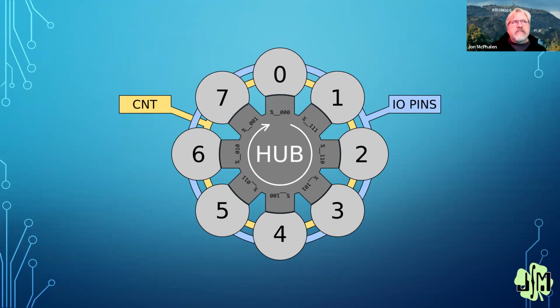And he has 16 channels of analog that he is using an external ADC because he already had that circuitry set up. And before, we needed 2 cogs to be able to read the ADCs and do a running average. So we actually will take the last 4 readings from an ADC channel and average them, and that's what we send out. So what that does is it just allows the ADCs to be really clean, especially with the joysticks. And in the P2, that's all in one cog and runs much faster. It's lovely.